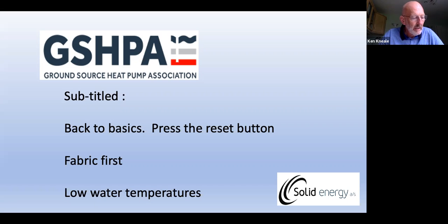My background has largely been on the dark side of the industry, installing and repairing large commercial heating installations with oil, gas and indeed biomass boilers. So my legacy on the planet will not be good compared to those who have been in the heat pump sector for many years. As a maintenance engineer, to solve the problem quickly and keep the occupants happy, we would very often turn up the boiler temperature and possibly even increase the speed of the pumps to come up with a quick remedy.